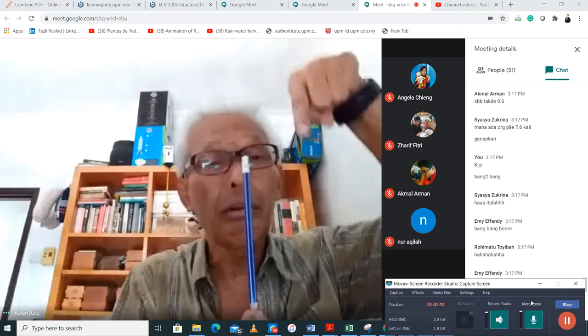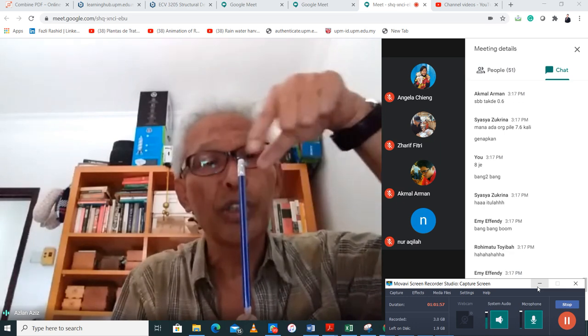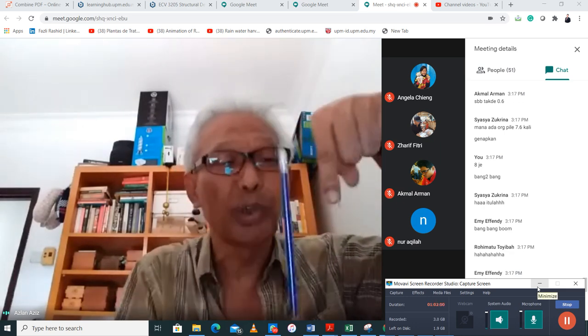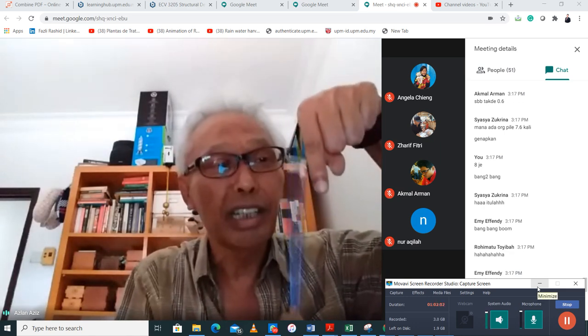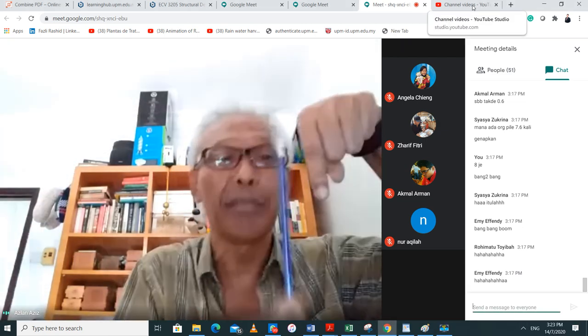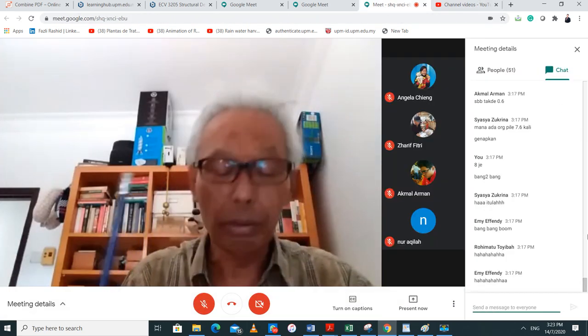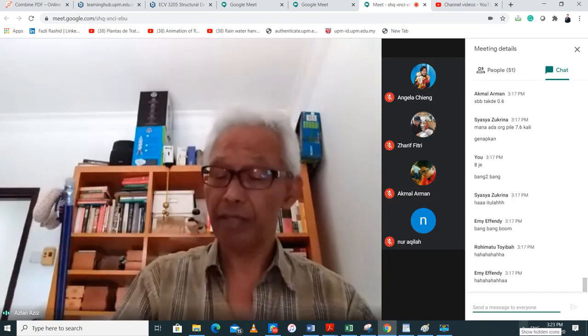Right now, I talk to you about shaft friction. This is a negative shaft friction which must oppose my uplift load. Here, the negative value is in this direction. It's okay. Why? Because I have this uplift load, so they cancel out each other. The uplift load is, again, 563.